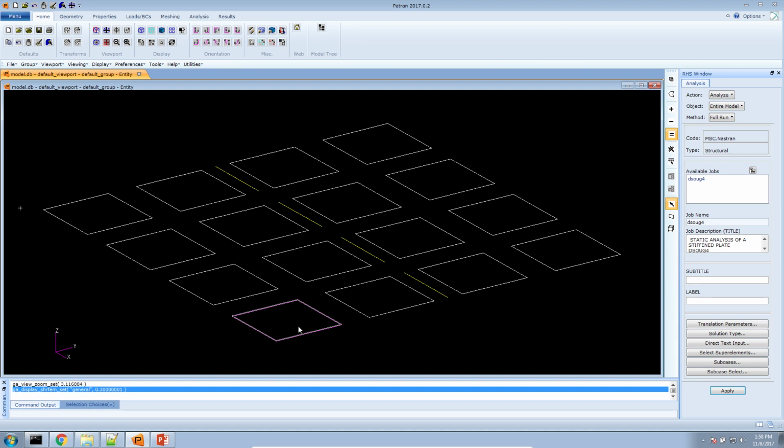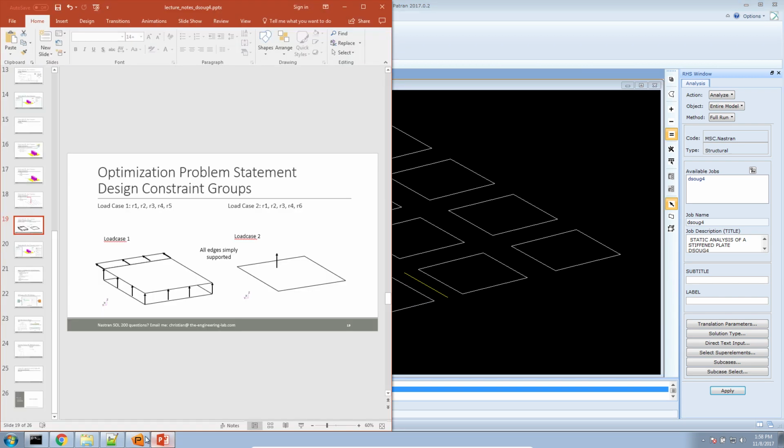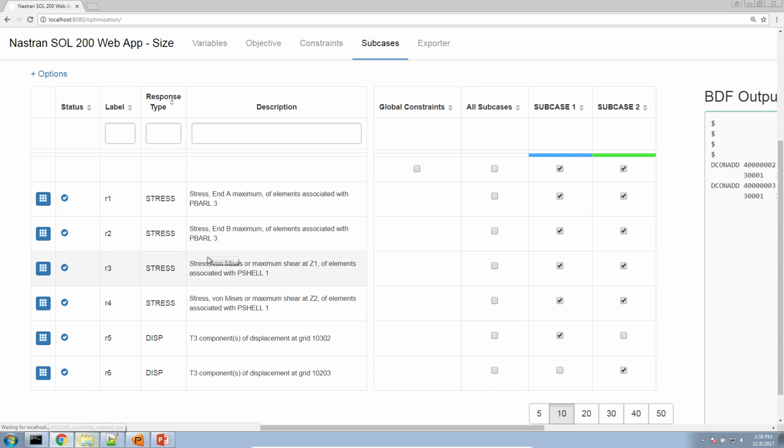So here we have actually constrained 16 elements. So although this looks like we have one constraint, we've actually constrained 16 element von Mises stress values. So here R3 again is linked to 16 element stress values. So is R4 and R1.